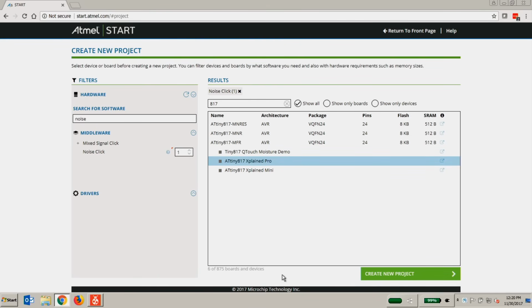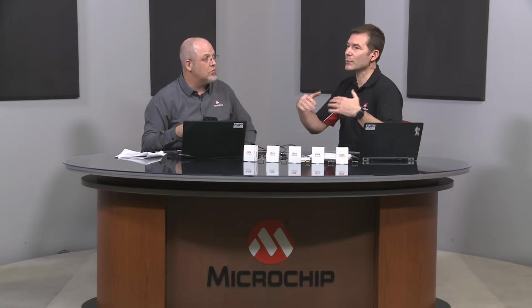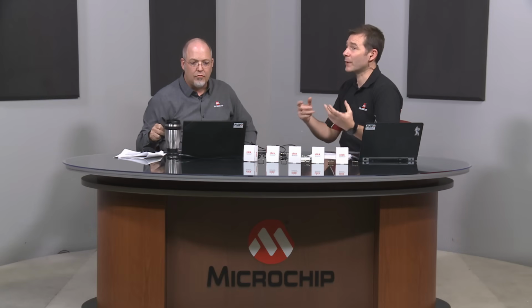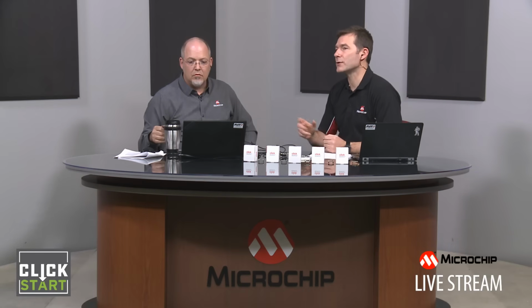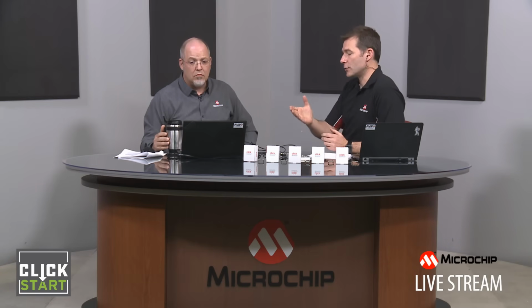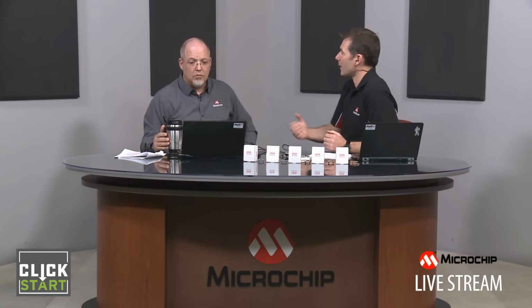Just a quick comment here, because you may see that some devices are listed in numerous lines. That would potentially be because they're from different packages. You're right. Different packages can actually have a different pinout or a different number of pins, so that would give you some variance there. Absolutely. So if you're in doubt, just look at the device you have and choose the right package. But otherwise, as Mark is saying, if you have a standard board listed, that would help you a lot.